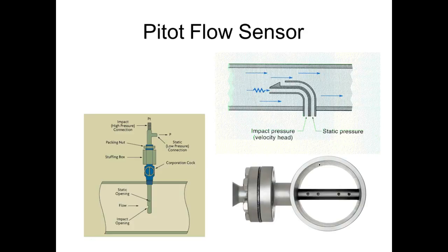What they do with the static pressure is, and it's really interesting how it works, it gives you an accurate reading no matter what altitude you're at, because your static reference changes with altitude, right? You understand? So if I go up, my static pressure goes down, and my pitot pressure goes down for the same speed. And the static sensors on the airplane are actually on the side of the plane.